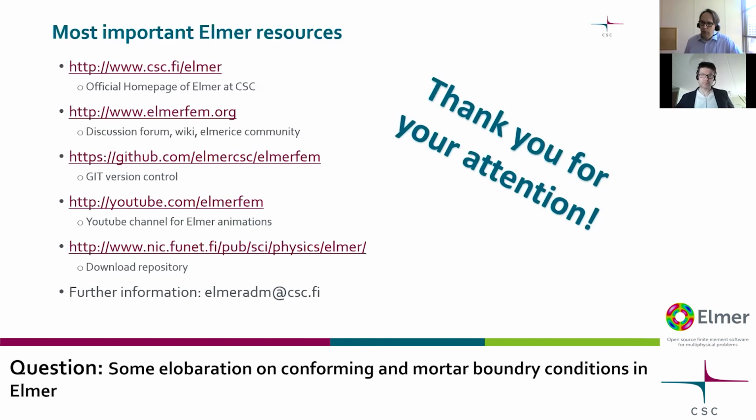Yeah, so in the last presentation, there was quite a bit about conforming and mortar boundary conditions. So yeah, in short, the conforming boundary conditions can be used if you can map 2 boundaries together so that they join or share the nodes or edges, and it's applicable both to the nodal and to the edge element problems.